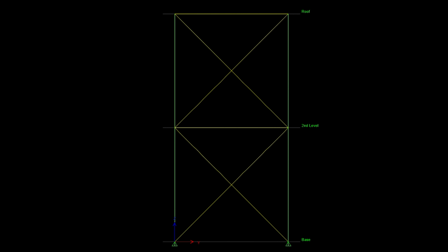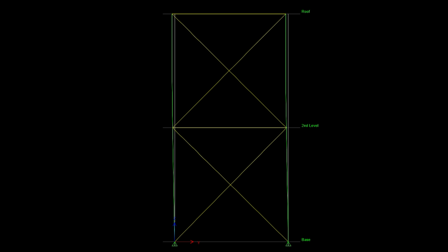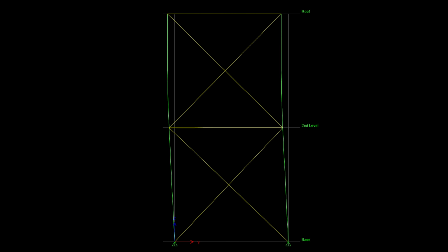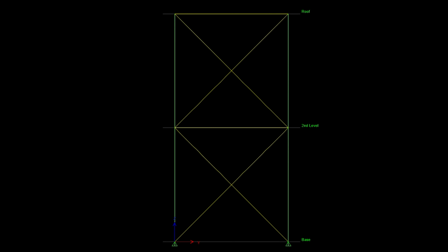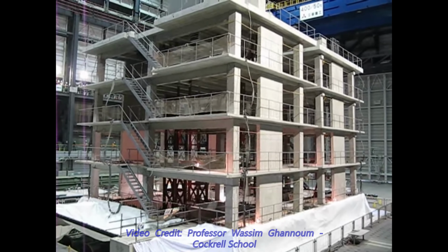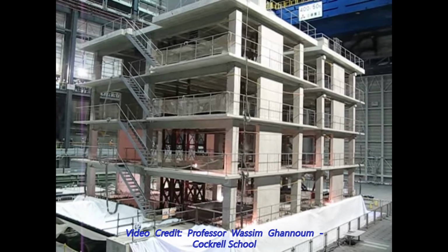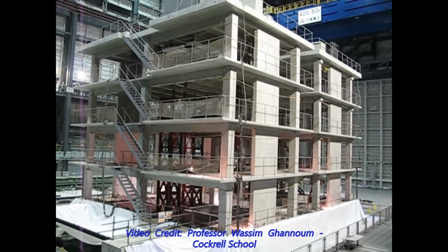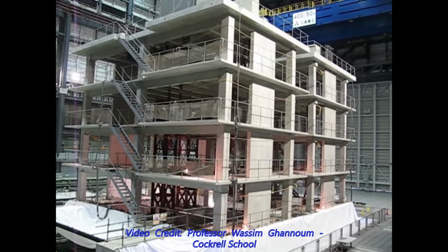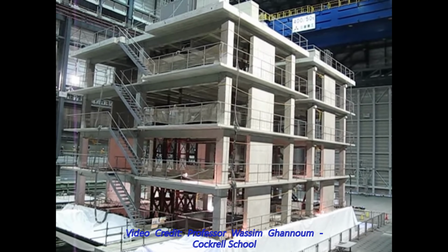When structures are impacted by seismic energy, they move and oscillate. The structure must be designed and built rigidly enough so that it can properly absorb and dissipate seismic energy without suffering a collapse. During large earthquakes, buildings are expected to be damaged. The goal of modern seismic design, however, is that at the very least, the building will not collapse after an initial shock, so that occupants can get out.